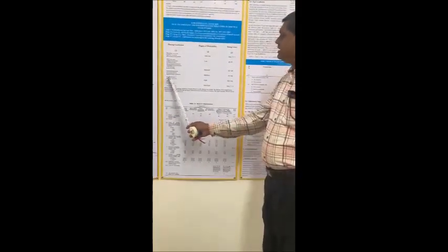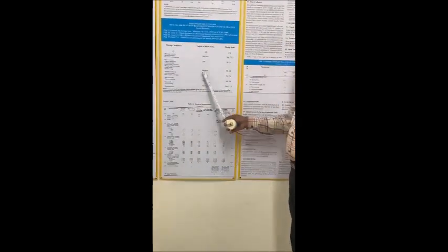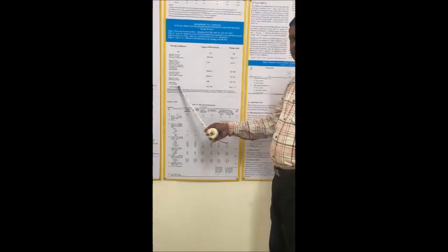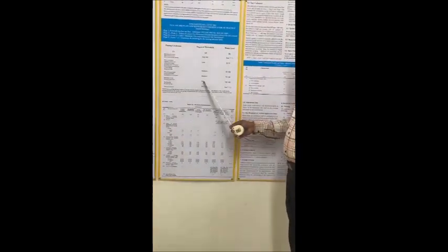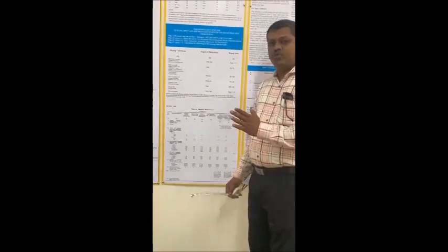Now the fourth is formwork, meaning pumped concrete. For pumped concrete the workability is medium, but the slump value is more than 75, up to 100 or even more than that. Last is trench fill, in situ piling, where the degree of workability required is high and it is 100 to 150 mm slump. And the very last is tremie concrete. For tremie concrete the degree of workability required is very high, and the slump mentioned, in clause 7.1.2, is more than 150 up to 200 mm.